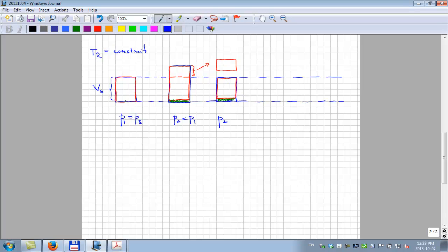So we're back to the same VS volume. We've removed this amount of gas, and what we actually measure in the laboratory is how many moles of gas were removed. We know the volume of that gas that was removed at pressure and temperature. Of course, we can convert the moles with our 23.68 number to an equivalent surface gas volume, standard cubic feet, standard cubic meters, right?